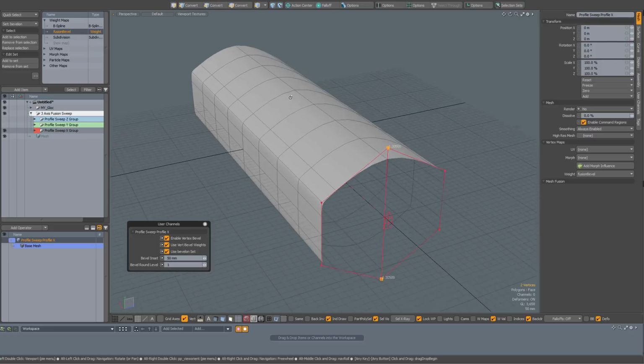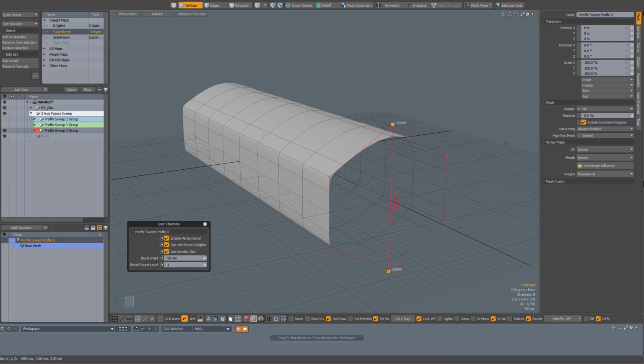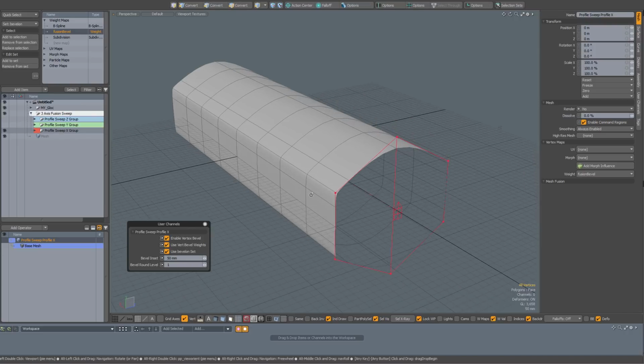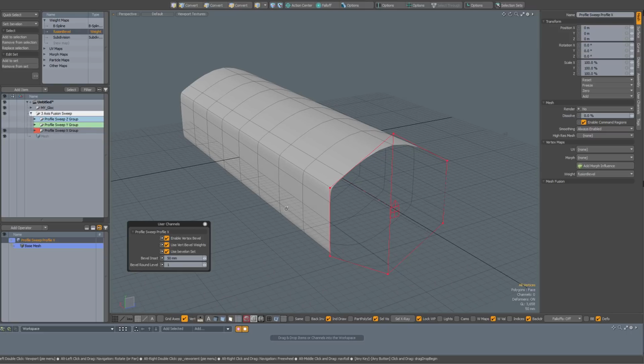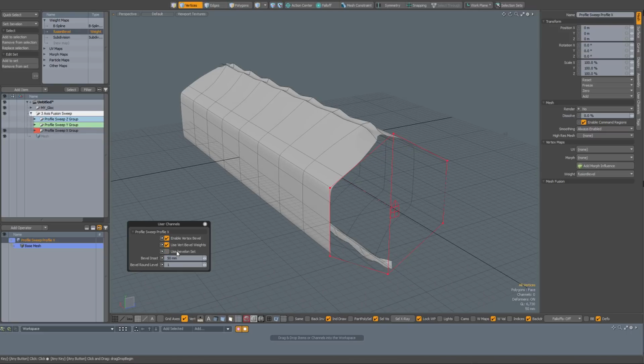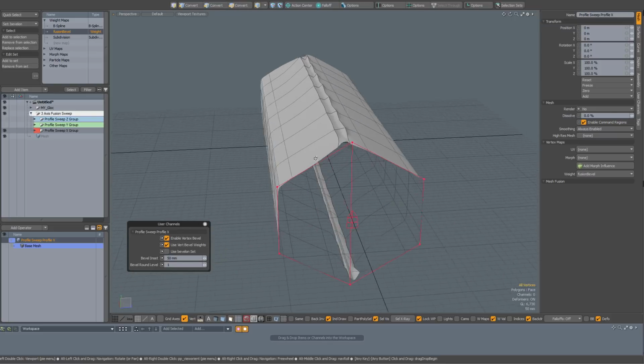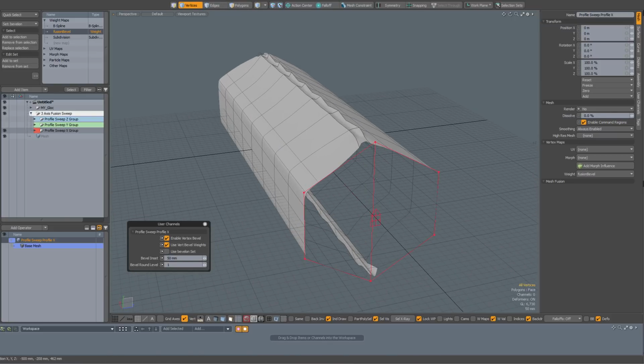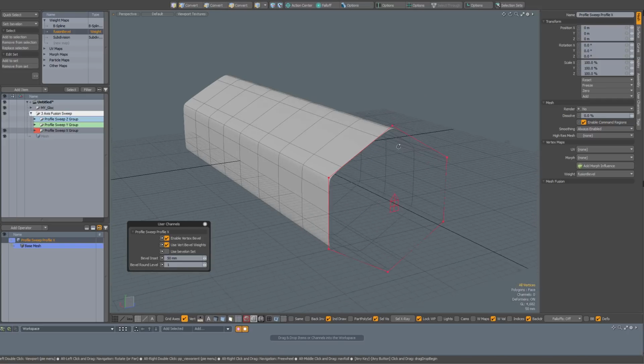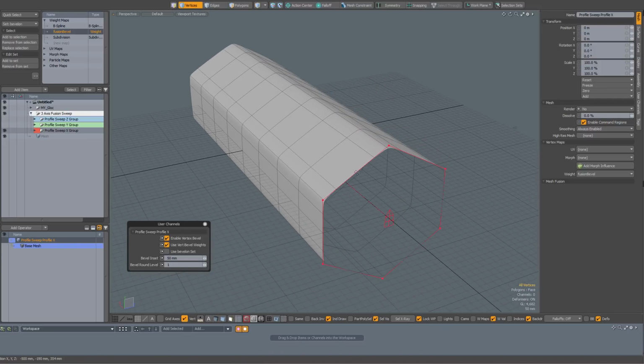Do some weighting. That will not matter since I have used bevel on set checked. So only the vertices that belong to the set are being beveled. So use vert bevel weights now, or adjusting the weights has no effect. If I uncheck use bevel on set, then you have a bit of a problem, and that is because of the edge. That is why I did an undo to get that edge back. So you should get clear of those edges, and then everything is back to normal again.